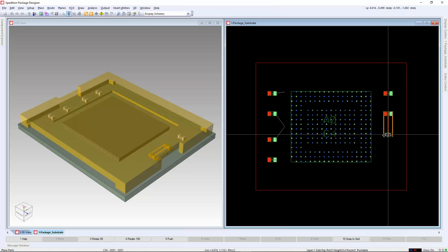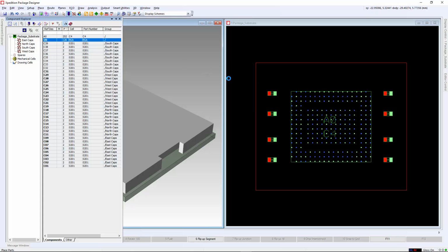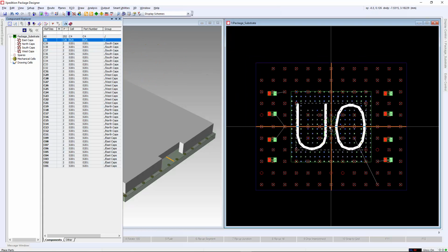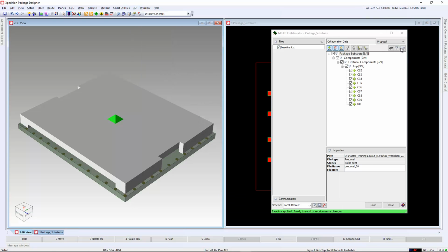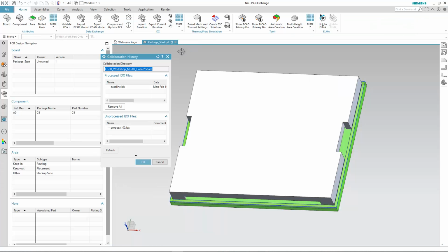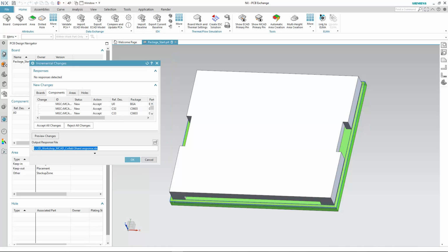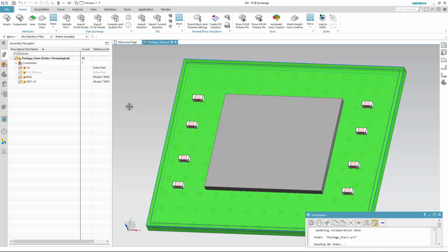With IDX, the user has the ability to preview information and identify what data set he wants to import and what data he wants to reject. We can also import the initial heatsink for placement studies. Here we have an online DRC that allows us to specify potential interference issues in the 3D domain between the mechanical library components like the heatsink and the capacitors placed within the design.